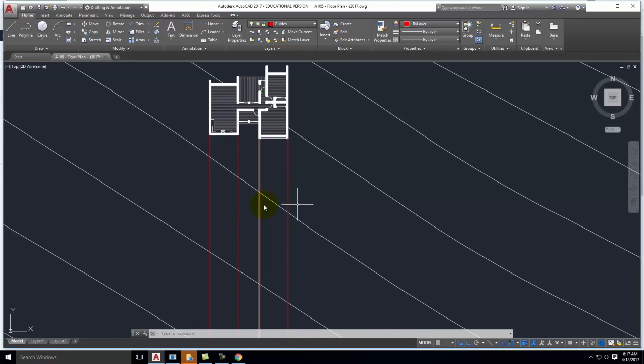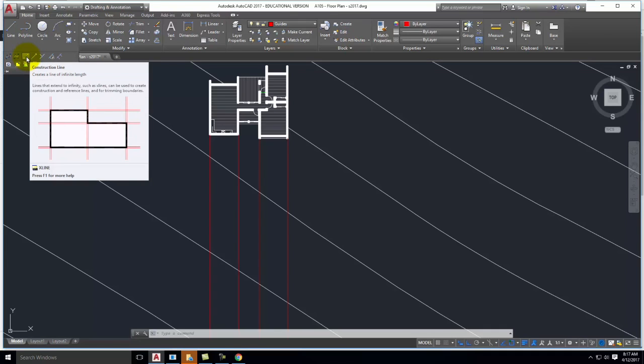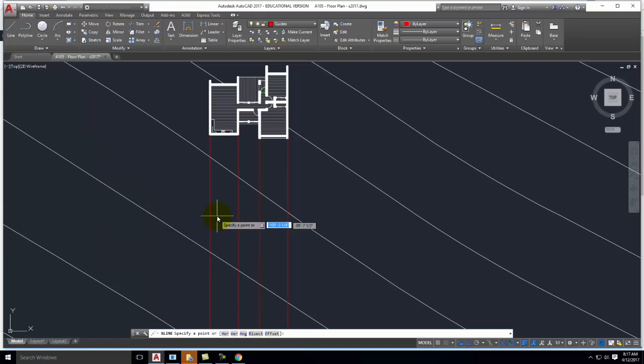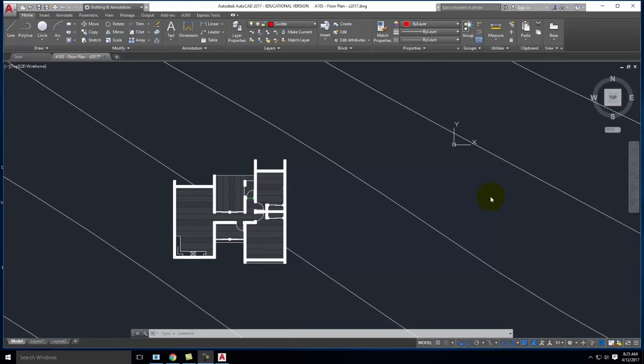And now I need a line that goes horizontally somewhere to start the base of my elevation. And so this time, instead of a ray, I'm going to use something called an X line, or a construction line. It's right next to the ray tool, and it's a dot in the center with 2 arrows going off of it. And essentially, that's a double-sided ray. It goes off into infinity in both directions. So I can either type X line, or I can click on the construction line tool. And it doesn't really matter where I...